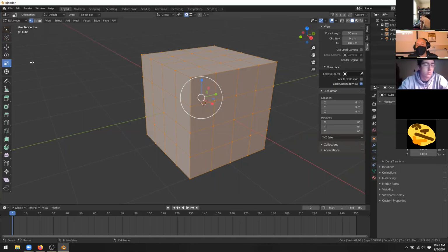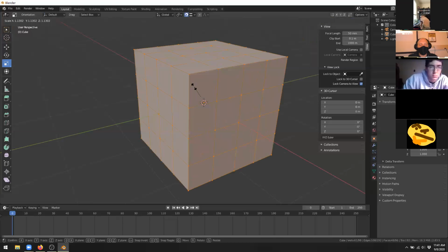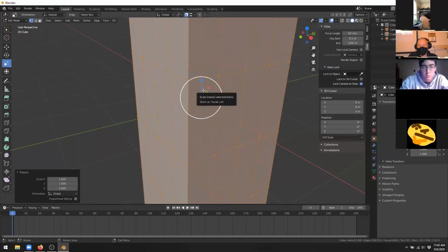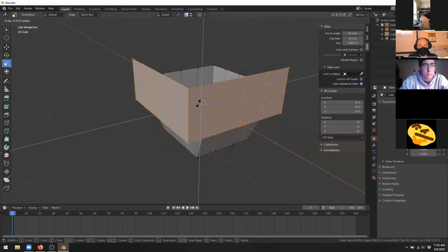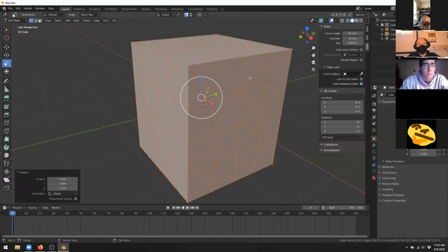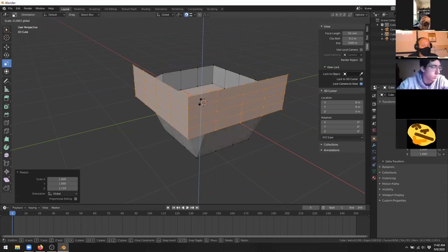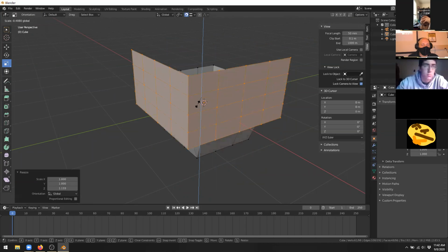And what I'm going to do is go into maybe my free transform tool. I'm not going to free transform along any one particular axis. I'm just going to be in this object and try to break it a little bit, or warp it past itself. Let's see, what can I do? Yeah, so notice how when I take it past itself, going down to the point where it essentially becomes inverted from its original self, the geometry gets really weird. Part of it is because things that weren't selected aren't moving, and the things that were selected are being transformed.